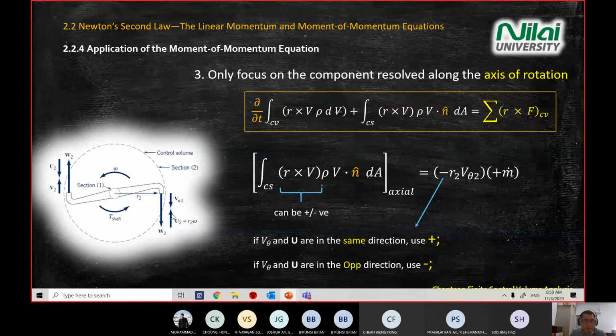However, for U2, if you sit at the reference point here and you look at the nozzle head, because of the reaction of the flowing out, the sprinkler will move backward. The sprinkler head will swing anti-clockwise, and your U2 will be opposite to your V2.